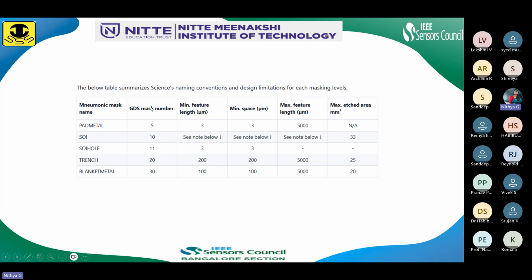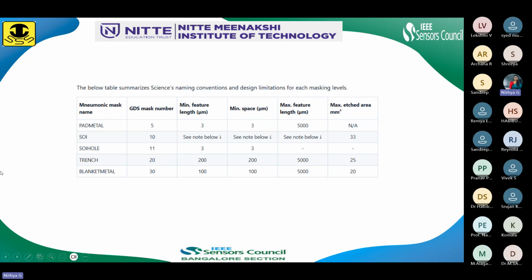Okay, so make sure what type of mask file you're going to create, whether it is a SIF format or the GDS format. If it is a SIF format, then you have to define the layer information with the help of their nicknames or the mask name. And if it is a GDS format, then you have to call the layers or add each layer's information by giving the numbers that define that particular layer.